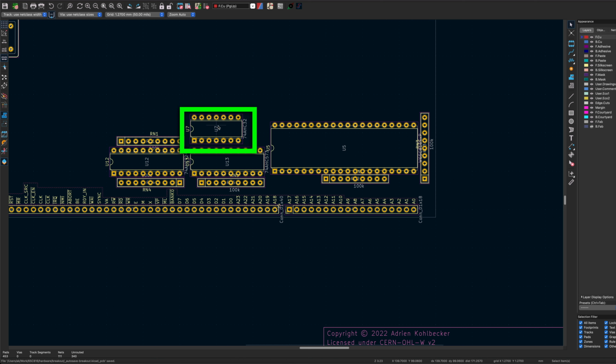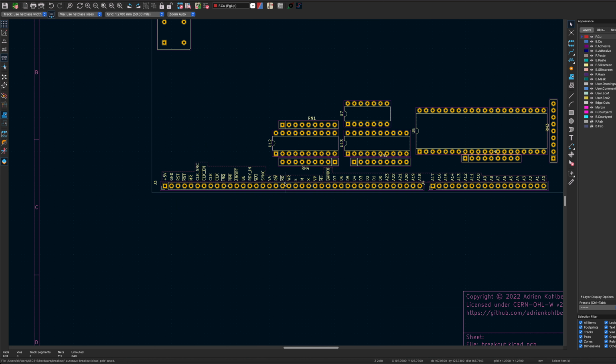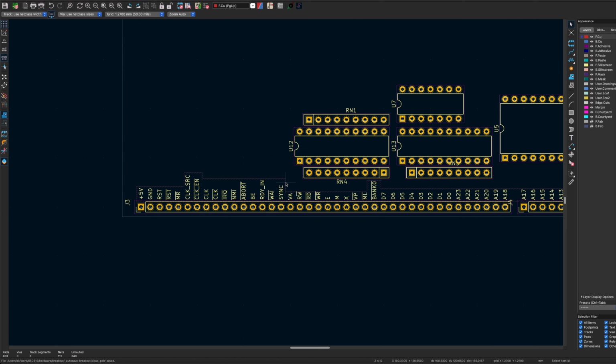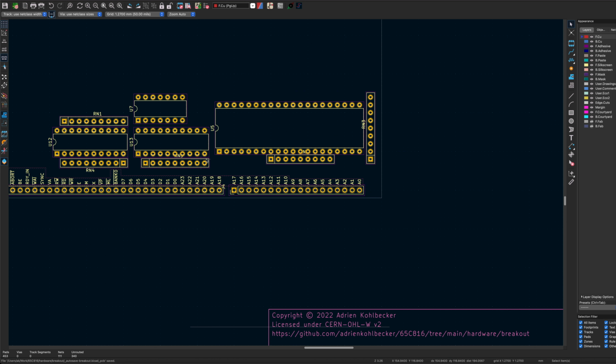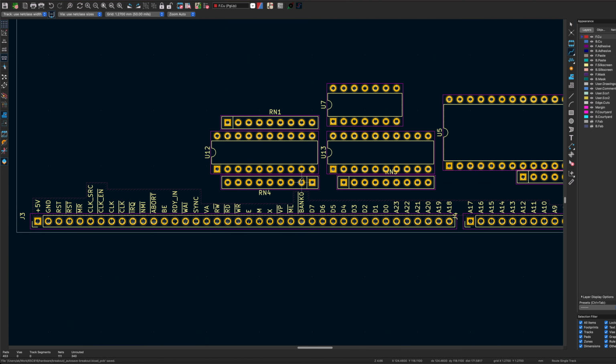And this is the first OR gate that helps us determine the bank 0 signal. So I've added my exclusion zone here so that we make sure that we don't put vias or pads or components where there is silkscreen. And I've added a legend for all the output pins here. Okay, so let me start routing this again, and I will start with the easy stuff.